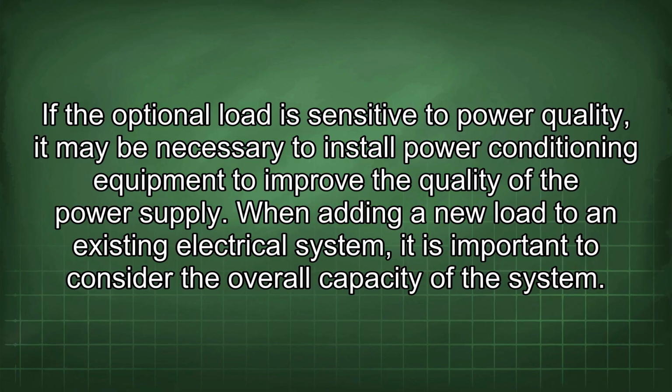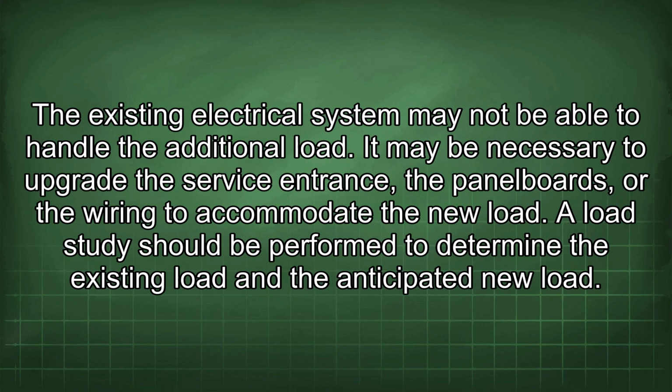When adding a new load to an existing electrical system, it is important to consider the overall capacity of the system. The existing electrical system may not be able to handle the additional load. It may be necessary to upgrade the service entrance, the panel boards, or the wiring to accommodate the new load. A load study should be performed to determine the existing load and the anticipated new load.